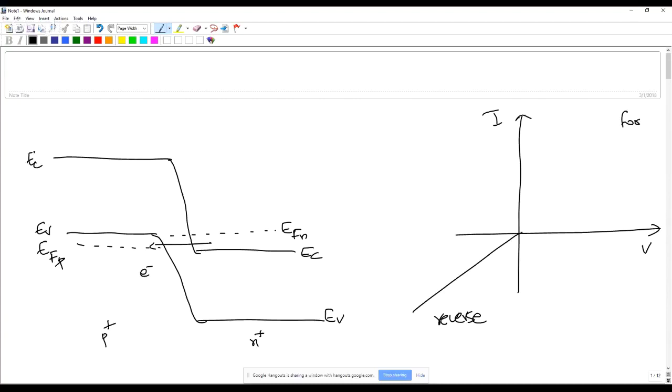So in the forward bias side, you have a situation where your current is increasing because the tunneling is still possible. Then I keep on increasing my applied voltage. EFN will start to shift up with applied voltage. There will be a particular point when your tunneling current is maximum, but as you keep on increasing the voltage up, as EFN keeps on going up, the tunneling actually starts to decrease. So you can end up with a situation like this.